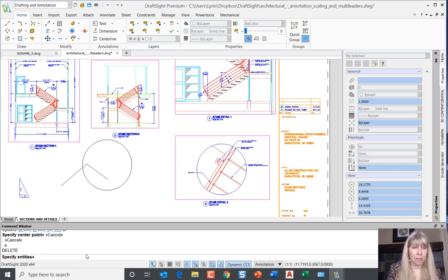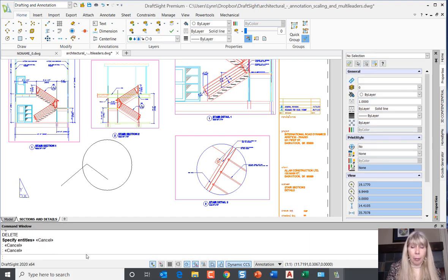So for example, if I wanted to do a purge, I type in purge. It actually knows that purge, can you see that in the lower left-hand corner? It executes a command called clean in DraftSight. I don't need to know that. It knows it. So you can still use the commands that you are used to, no problem. It's easy to make the switch from AutoCAD to DraftSight. It will do the work for you, which is really, really fabulous.